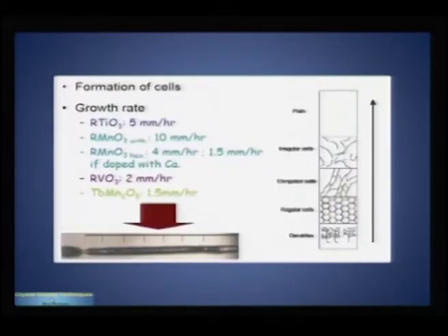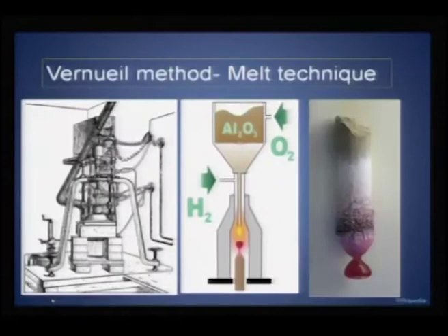Typically the growth process also involves the way you try to grow it in terms of growth rate. Manganates are much more faster, we can try to grow at a much faster speed, but titanates are usually a time consuming one. The sort of rods that we can grow, single crystal manganates or vanadates, typically looks like this. You can grow such long ones, and then those are nearly 99.9% dense. So, this sort of single crystal rods can be usually achieved using this floating zone method.